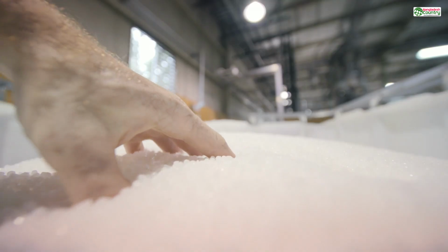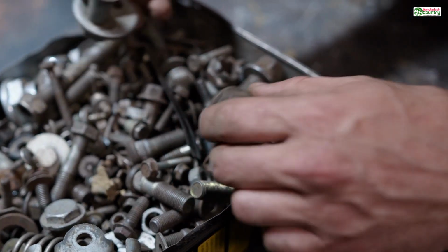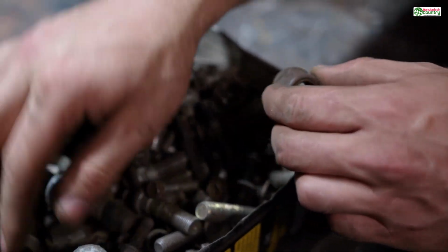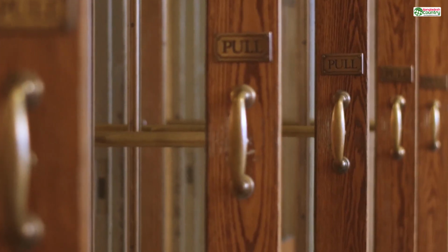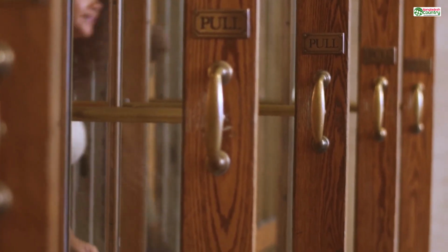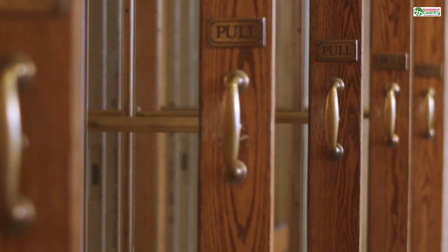Question 2. What environment will it live in? If it's going to be in a hot car or near a motor, PLA is out. You'd need ABS or PETG. If it's going to be outdoors, you'll need something UV resistant. If it needs to be food safe, you look for a certified PETG. The environment dictates the material.